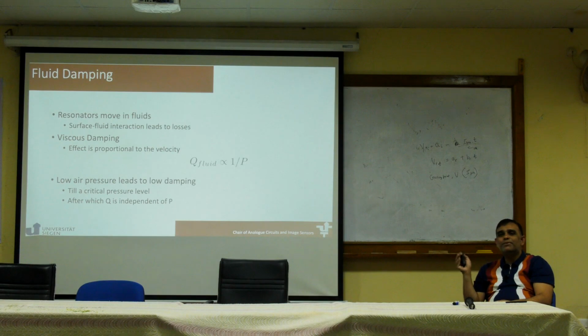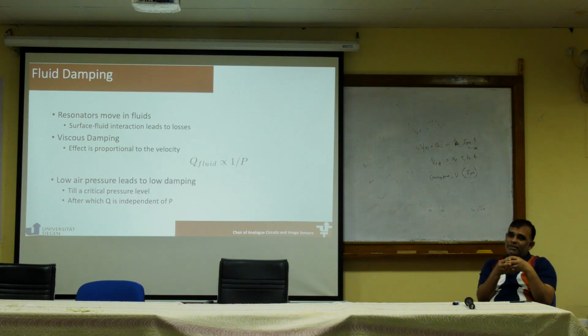Now, the quickest way to solve air-based fluid damping is actually to take these sensors into low pressure. So you can put them in low pressure chambers, reduce the atmospheric pressure, there is less air there, there will be less damping.